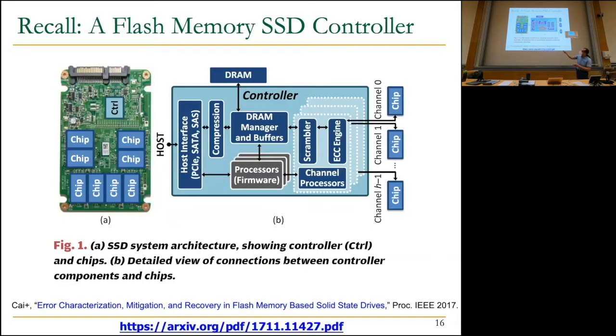And this is the host. There's an interface to the host. The host is not shown here; it's really the host processor. And you can see that flash memory has its own DRAM so that it can do buffering of the data. So even though these are the flash chips, to control the flash chips, you need an entire system, and also other memories as well. You can think of this as a memory hierarchy within a memory hierarchy. You have this entire system over here, but to make flash memory operate, you have another memory hierarchy, another system to make it work. And that's what's fascinating, actually.